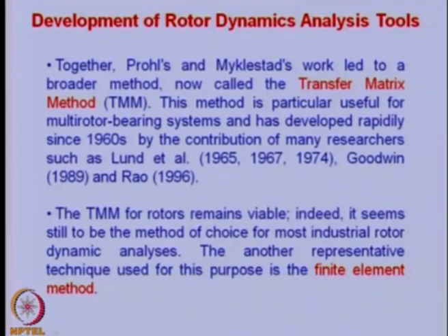This method is particularly useful for multi-rotor bearing systems and has developed rapidly since the 1960s through the contributions of many researchers including Lund, Goodwin, Rao, etc. The TMM, or transfer matrix method, for rotors remains viable. Indeed, it still seems to be the method of choice for most industrial rotor dynamic analysis. Another representative technique used for this purpose is the finite element method.